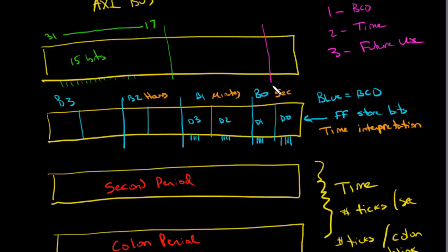And so I'm just arbitrarily picking these things, bits 1 to 0 would be the mode. And if you're in mode 0, then we're going to drive these values out to the anodes. And if you're in mode 1, we drive these through the BCD controller and out to the cathodes and anodes. And if you're in mode 2, you're in the time interpretation. But then we'll have to take the time and drive it into the BCD module, and then the BCD module will drive the cathodes and the anodes.